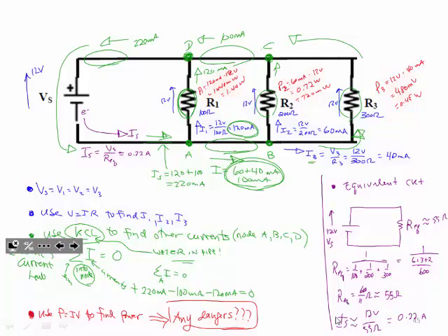All right, see that? Now, if you look, what about these other ones? Resistor 2, I had running at 720 milliwatts. That's 3 times. All right. This one's at 480, which is about twice. But you notice that's the ratio of our currents as well going through there. So this one is double. So let's see what this one feels like. This one I can hold my finger on before I feel it. Try that one.